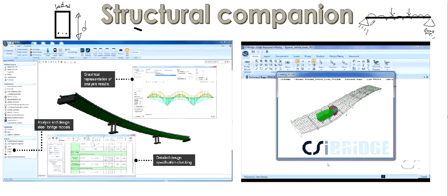To determine all this information, you need to calculate the moment, the shear forces, torsion, and all these things, to determine the reinforcement, the concrete, the depth, the breadth, everything. Those forces, I'll be discussing later. Those forces are very related to the reaction you calculated here.